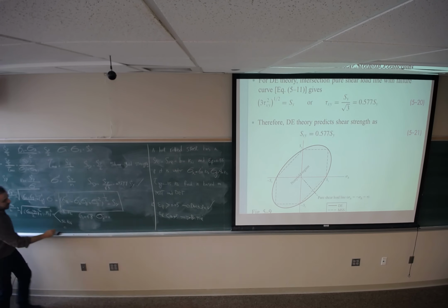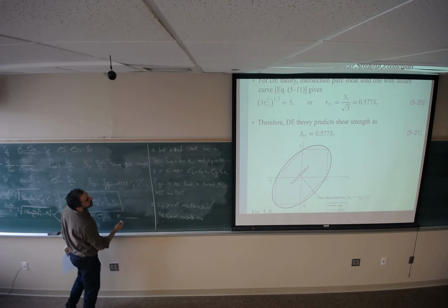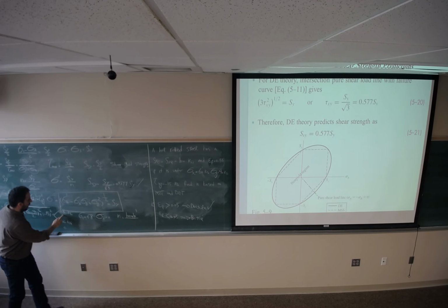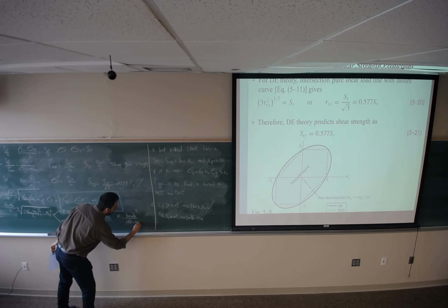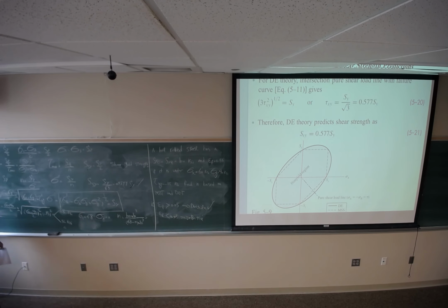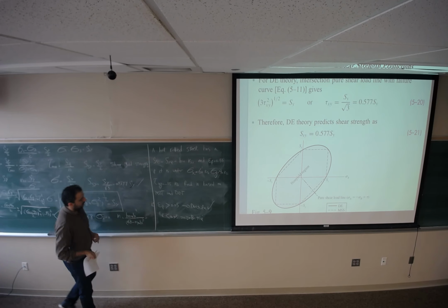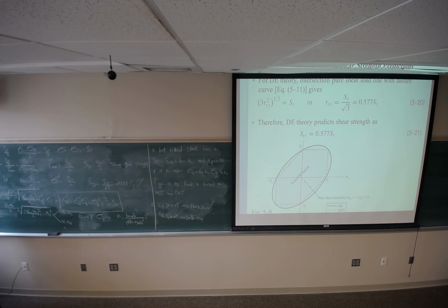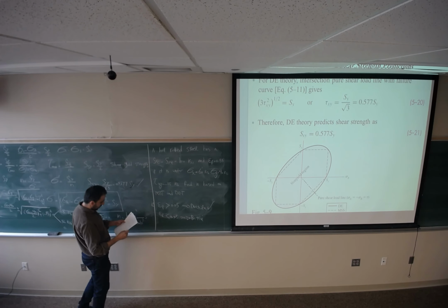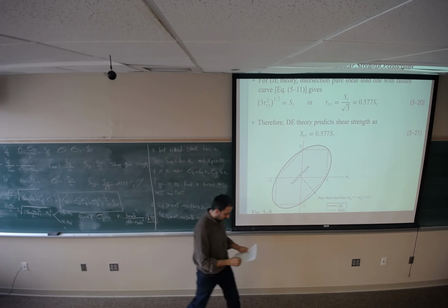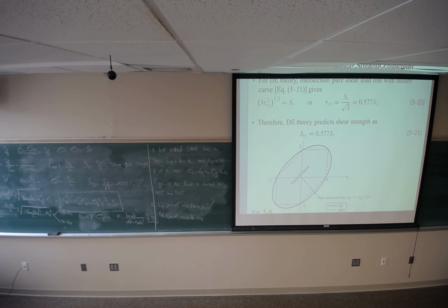To find n, I divide SY, which is 100 kpsi, by 68 minus 0. I just changed everything to psi, but I know that both are in psi, so I could cancel them out. So 100 divided by 68 is going to be 1.47, based on maximum shear stress theory. Good.